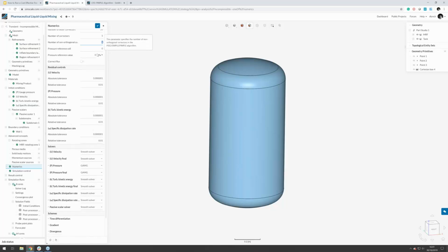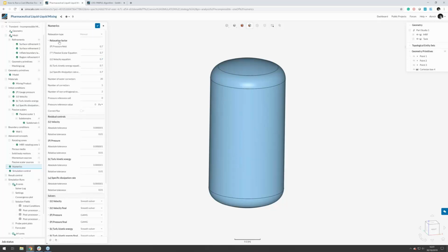And then also we've got relaxation factors. So the idea is a typical transient simulation running for 1 outer corrector is always going to be set at 1. If you're running at more outer correctors, so you're going to be correcting it and solving little tiny steady state simulations, I say, then what you're actually going to want to do is set some relaxation factors so that it's not taking the entire solution as before into your next step.